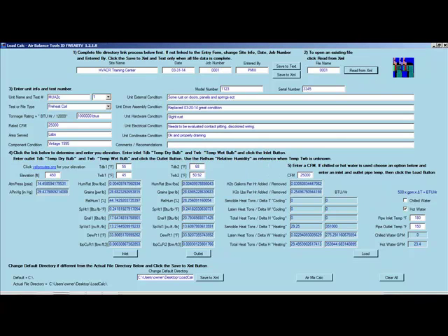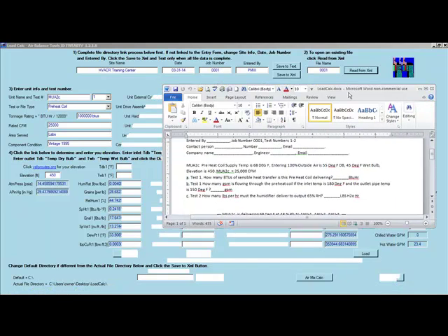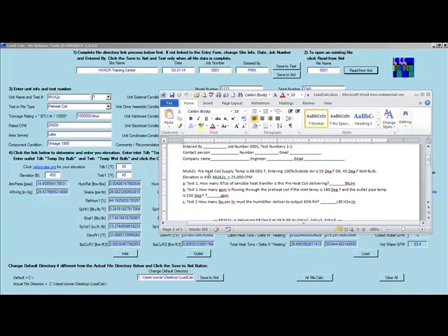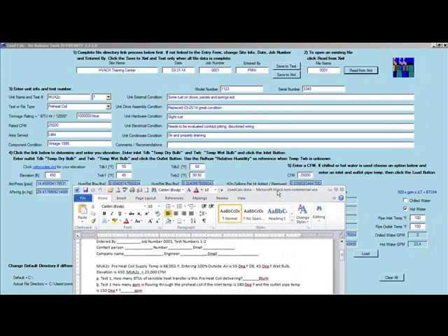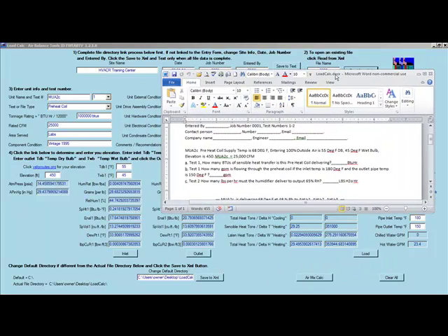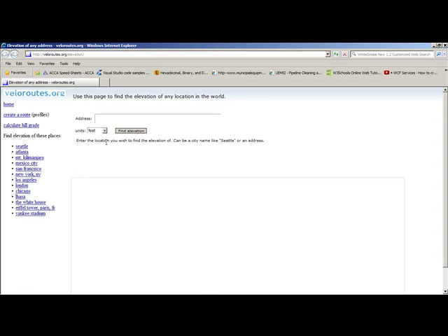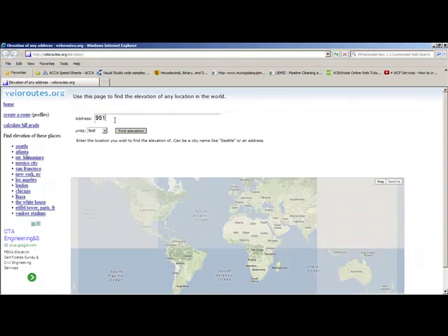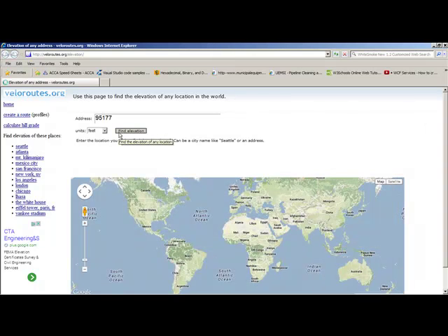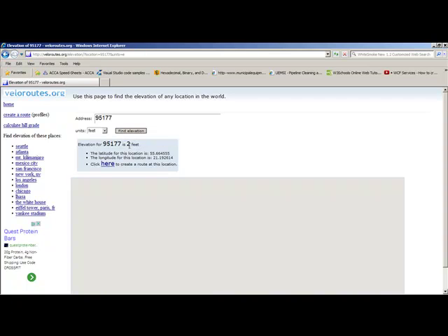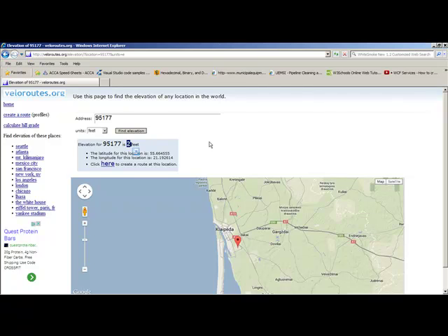So now we have our parameters here. Our preheat coil is 68 degrees. We have entering air 55 at 45 wet bulb, and an elevation of 450. If you weren't sure what our elevation is, we can always go to this link here. Type in your address, zip, city, whatever, and it'll give you your actual elevation level.